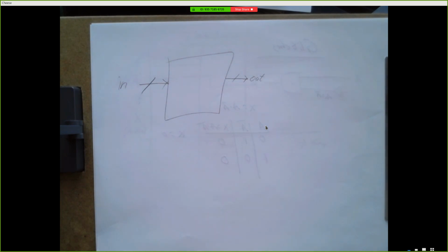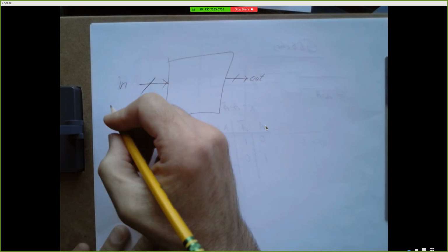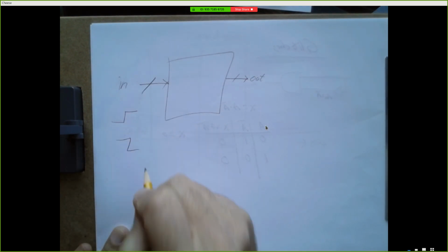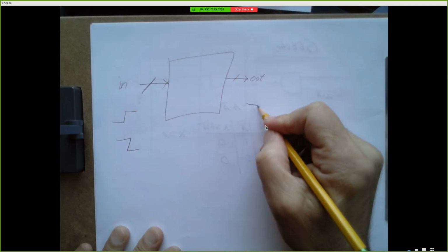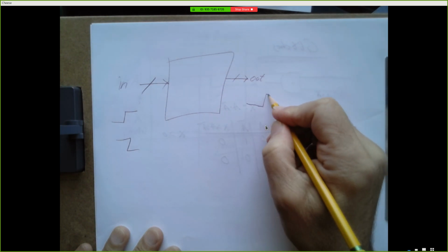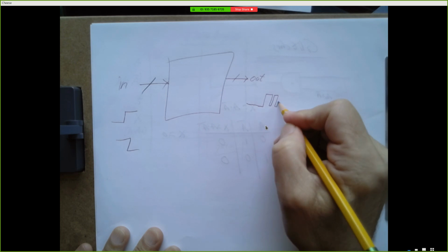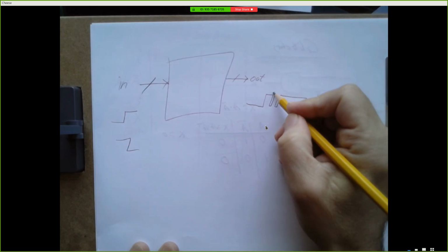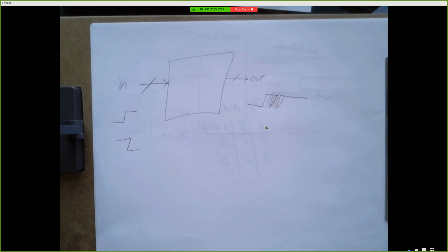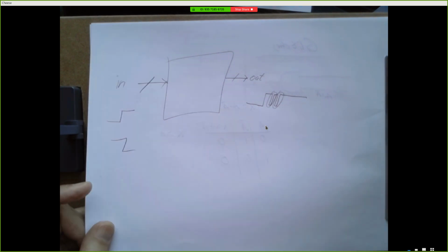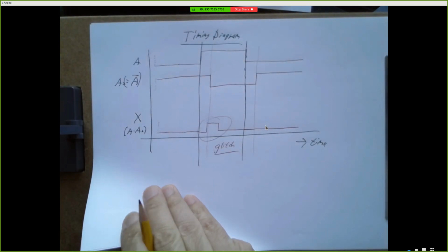And normally, you don't change your inputs, your outputs are stable. The potential for glitches is when one of our inputs changes, it goes high or it goes low. Our output might change from a 0 to a 1, but it might go through intermediate values along the way. Right? And there's your glitches. So there's ways to deal with this. One way to deal with this is through some clever software.